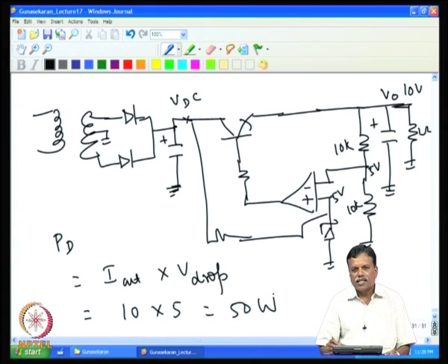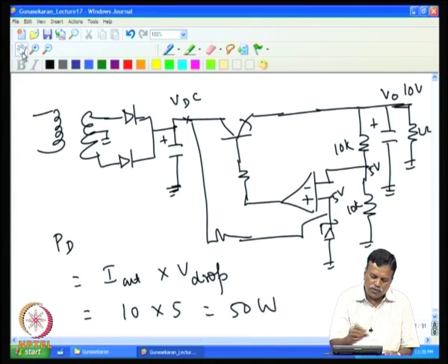already seen earlier that this kind of power dissipation will take the junction temperature to a very high value, because junction temperature determines the life of the transistor, and the reliability of the instrument depends very much on the power supply, and particularly the life of this transistor decides eventually the life of the equipment. So, one has to make sure that the junction temperature of this is normally not more than 80-90 degree to get long life. In that case,